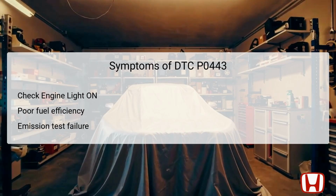The DTC P0443 can manifest several symptoms that can affect the vehicle's performance. One immediate sign is the illumination of the check engine light on the dashboard, indicating an issue that requires attention. Drivers may also notice a drop in fuel efficiency as the EVAP system seeks to manage vapor emissions effectively. If the malfunction leads to excessive emissions, the vehicle could potentially fail emissions testing, causing complications for the driver. While these symptoms can vary from vehicle to vehicle, they commonly arise in conjunction with the DTC P0443 and should be considered during diagnostics.